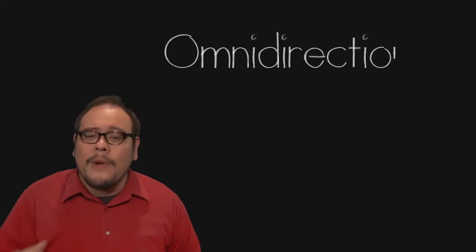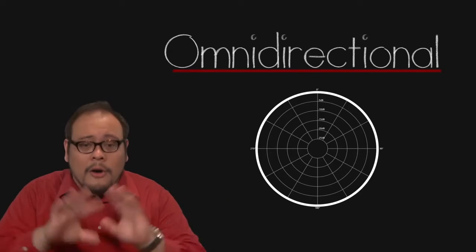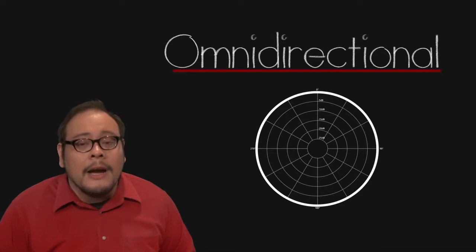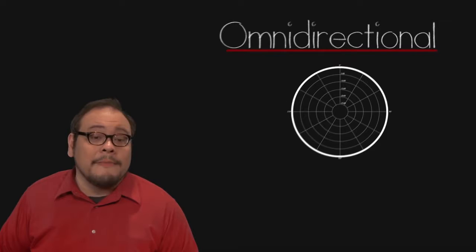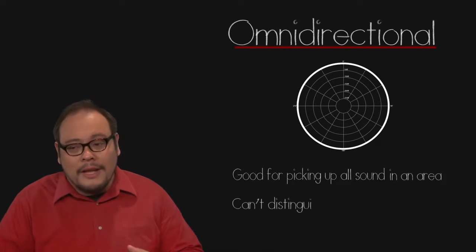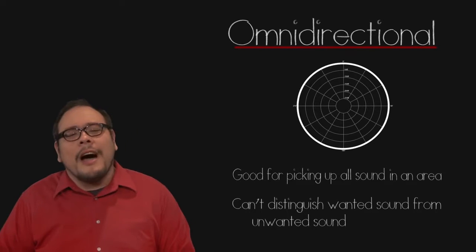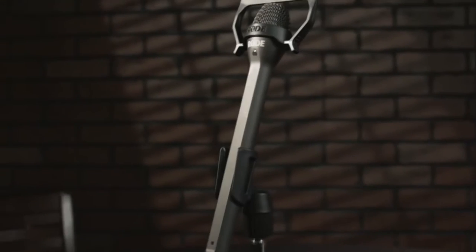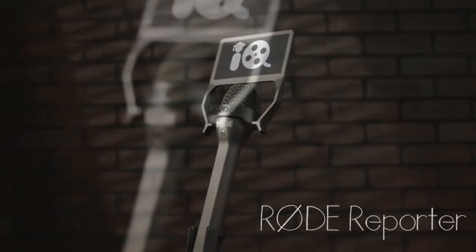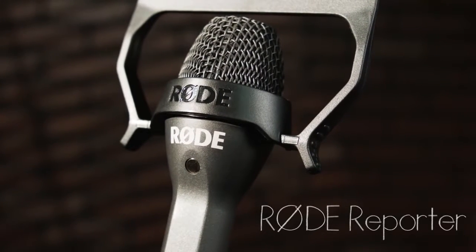The omnidirectional pattern means the mic is responsive to sound from all directions. You don't have to be on axis in order to be picked up. These mics are useful for picking up sound in a general area, but the drawback is they will pick up all the unwanted sounds in a general area. An example of an omnidirectional mic is this Rode Reporter mic, which is designed for news interview applications. You don't have to point it directly at the source, you just have to get it close to the speaker.